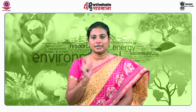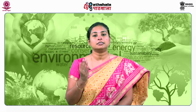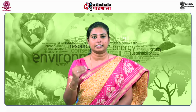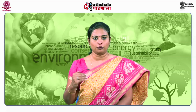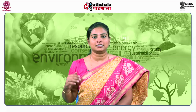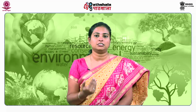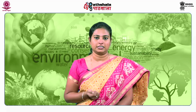Now, as I told you, the second unit in the activated sludge process is a clarifier or settling tank, where the sludge formed in the aeration tank is brought into the clarifier and allowed to settle by providing a retention time of around 2 hours. The sludge settled at the floor is then removed from the clarifier, and a part of it is recycled back to the aeration tank as an inoculum for treating more leachate, and the supernatant generated from the secondary clarifier is taken as runoff or effluent.